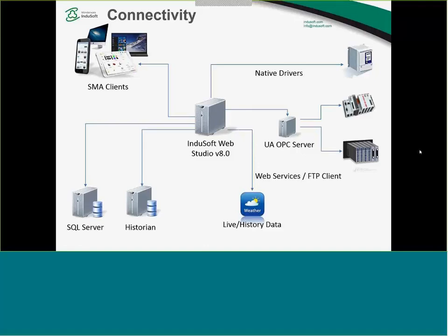If you had to rely on the DCOM technology for remote OPC connections, it would be a big challenge, if not a showstopper, for a project this size. So it was really important to be able to use OPC UA, which makes remote connections very easy, but at the same time very secure for us.